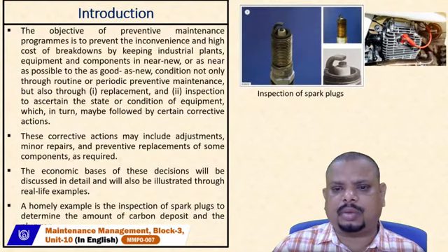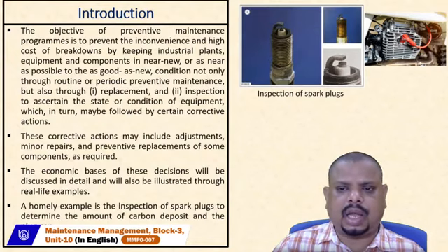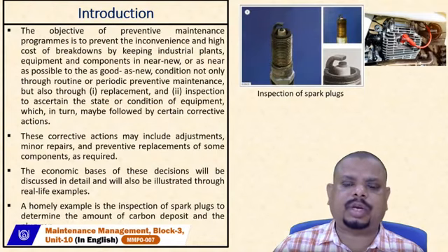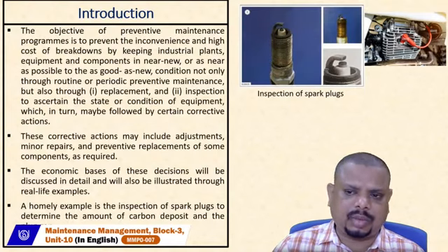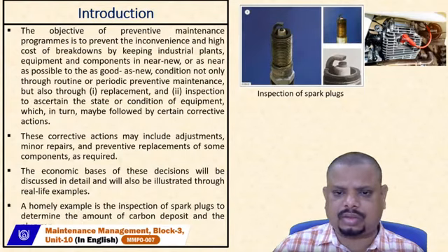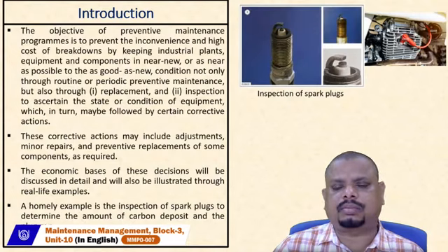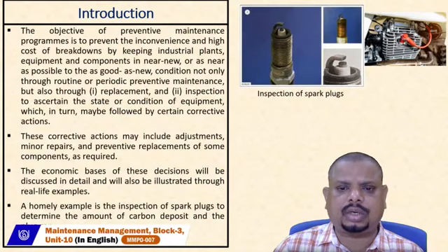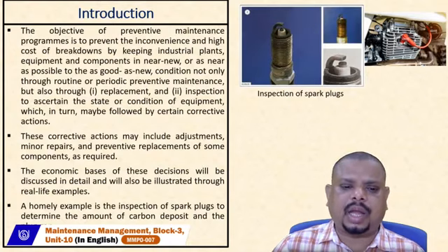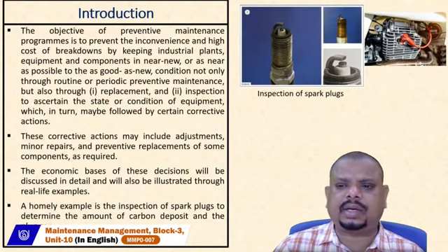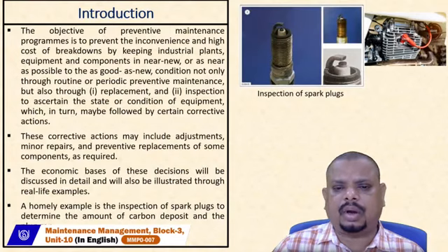That means you have to clean the carbon deposit on the upper part of spark plugs, and if required, you must go for replacement of these parts. If you observe the durability of use in the case of two-wheelers, it depends upon the replacement policies for a specific part which is known as spark plugs. During the inspection stage, you have to identify the different layers of carbon deposit on the upper surface of spark plugs, and by inspection you can easily identify and take the decision whether to go for minor repair or a replacement policy for the spark plugs.